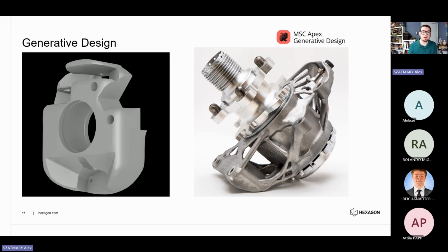There is Apex generative design, where instead of saying, here's my part geometry, here is my loading, where is it going to fail? We could instead ask the question, here's the overall envelope where we want the part to fit. Here are the interfaces, the loads, and my failure criterion. Solver, you go figure out which shape the part could have.